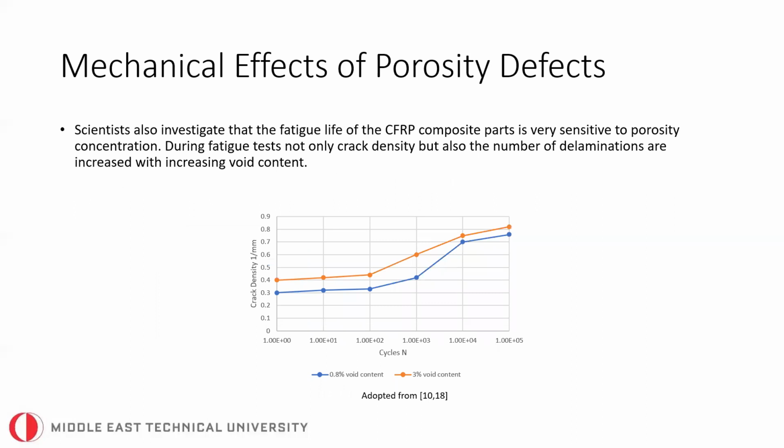Scientists also found that the fatigue life of carbon fiber reinforced plastic composite parts is very sensitive to porosity concentration. During the fatigue test, not only crack density, but also the number of delaminations increases with increasing void content.